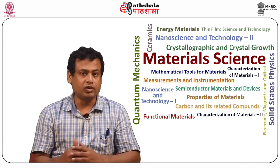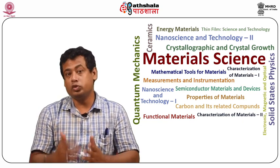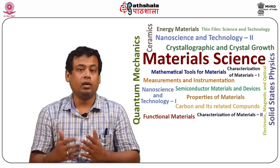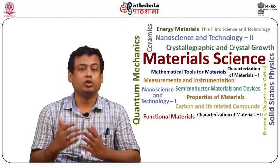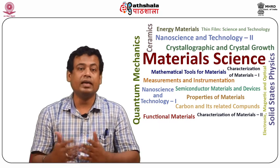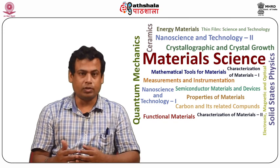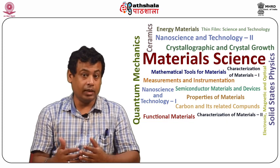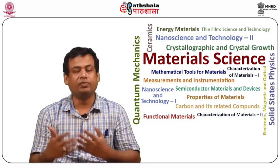Several lithographic methods are developed with different resolution, reproducibility, speed, simplicity of processing and acquisition costs, etc., by using different sources of energy. The process of utilizing a light source for patterning is termed photolithography, and the utilization of energetic beams as sources is nomenclatured according to the types of energy source.